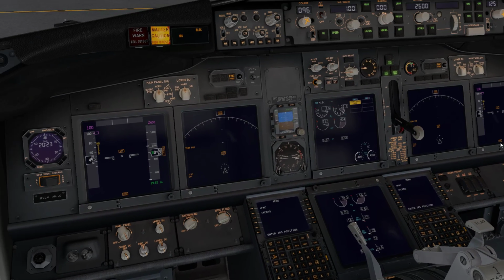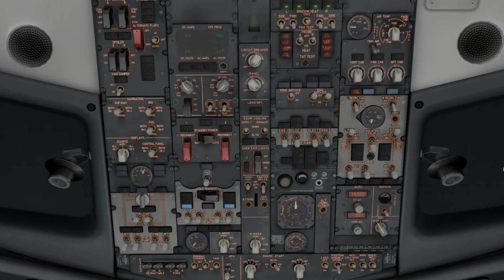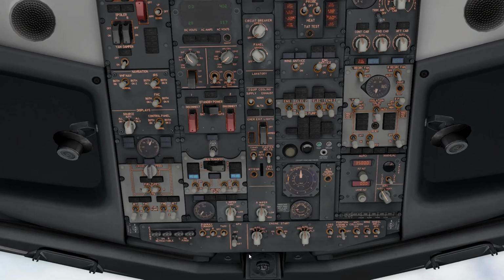That introduces the fuel. You'll see the exhaust gas temperature in the forward center panels start increasing. The N1 is starting to come up. You can expect it will stabilize at about the same point that engine number 2 is once it's been idling for a moment. I heard my kickback overhead, so looking back to our overhead panel, both starter switches in the bottom of the overhead panel have gone back to auto. For takeoff, those will be set to continuous, but we don't need it for now.